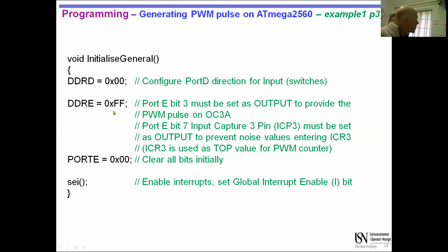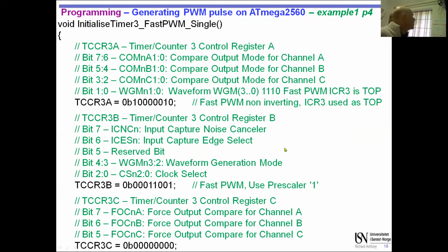Okay, so you obviously have to think about the whole chip and what you're doing. We need interrupts for the timer. No, we don't. Sorry, we don't need the interrupts for the timer. We need interrupts potentially for the switches. Not necessarily for the timer in this case, actually. It depends how we're using the switches.